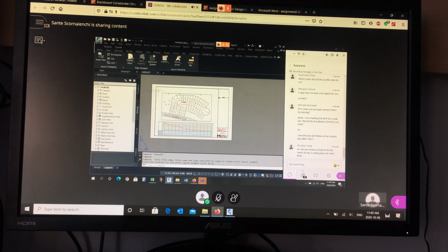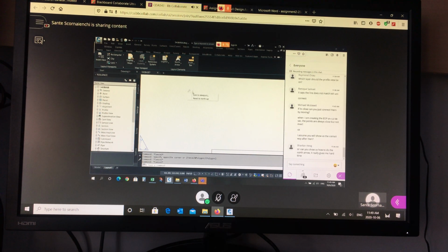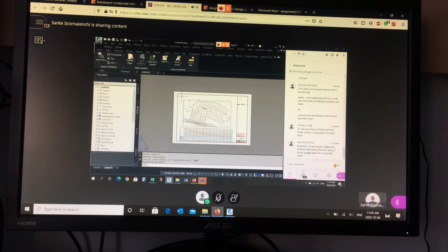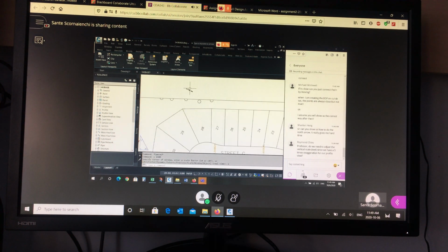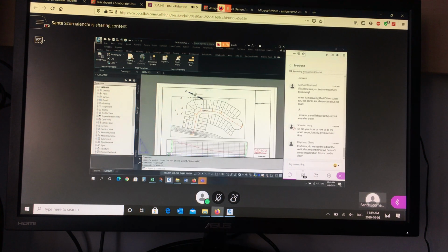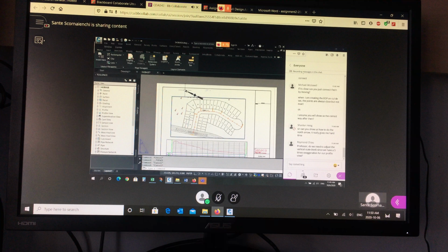And when you're done, it's too small. And the reason it's too small is because it thinks it's in millimeters. You're drawing in meters. So when you click on it, to find it, when you click on it, you can change the scale. You can change the scale, or you can just use the AutoCAD scale command. Scale, pick it, pick a spot nearby, and scale it by 1,000. Make it 1,000 times bigger. It might disappear off the screen. Okay. You might need to make it bigger. And then you can use this grip edit to make it bigger. Okay? But that rotation is tied to that north direction of the viewport. Okay? So if you don't see it, if it comes in small, it's because it was drawn in millimeters.